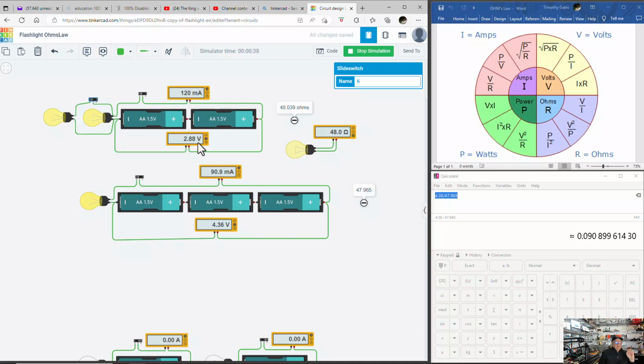That's because our voltage dropped, because as we increase current going through the light bulbs and through the battery, the internal resistance that you can't see and you can't really measure, actually we could, but we're not going to right now. But that increase in current flow through the batteries drops some of that 3 volts internally in the batteries. It's called internal resistance. So this is a perfect demonstration of that principle. Now we're going to do one more thing.